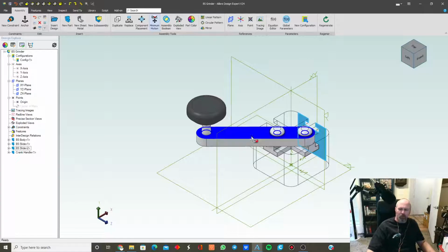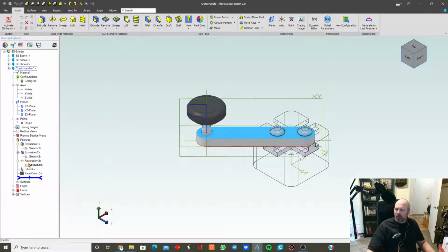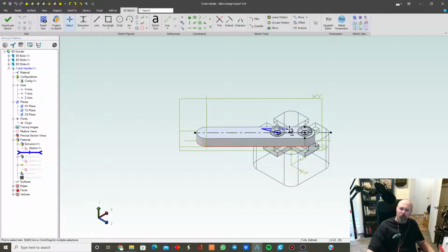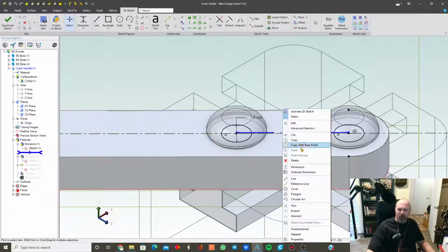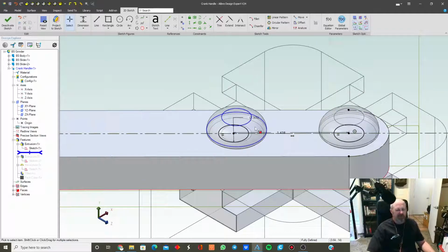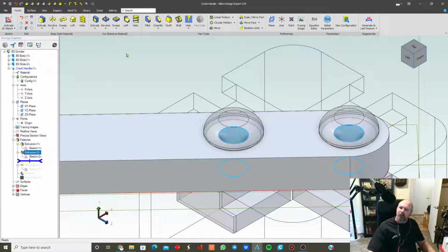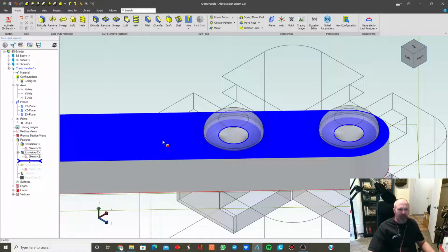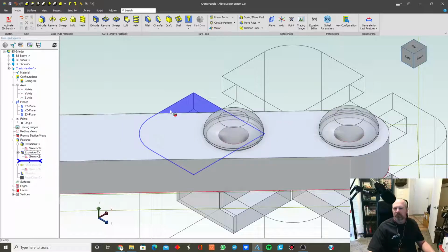So we can do that. We can go through, right click it, edit here, right? And then we go to our extrusion. Find that particular drawing where you drew those two holes, right? So let's change that dimension. Edit, 1.4375. Okay, so 7/16. Deactivate, and see it automatically updates everything, which is kind of neat because it gives you the chance to edit stuff right on the fly.